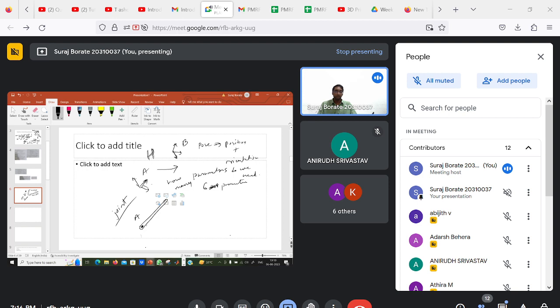That joint will be defined somewhere, and we do define something about it. What do we define about it? We give it a nature, like we say it is a revolute joint or a prismatic joint. When we do this, we restrict the number of degrees of freedom of this point A, and depending on how many degrees of freedom are restricted, these six parameters can be reduced.